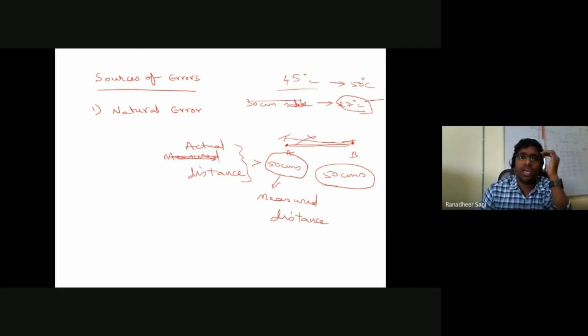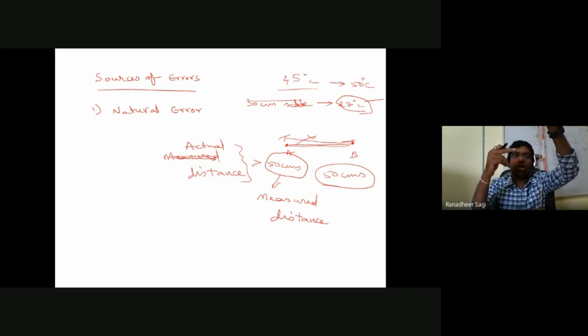Likewise, sometimes when you are trying to locate the position of some point in the field, there could be an issue because of wind and various other aspects. So when you are trying to locate the position of that instrument with the help of what is called a plumb bob, let's say, for example, this is what we call a plumb bob, a thread connected with a bob at the bottom, relatively heavier in weight. This bob is made of mild steel. Because of the heaviness of the weight, this bob always tends to show us the direction of gravity. Your bob will always get suspended towards the direction of your gravity.